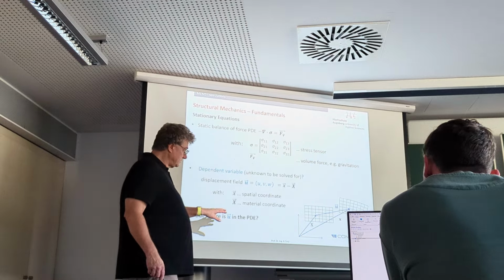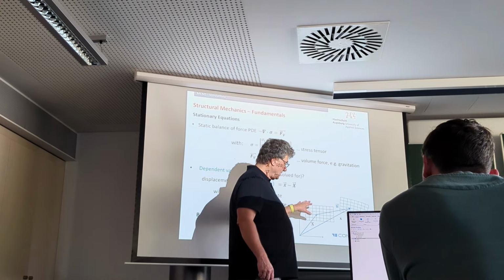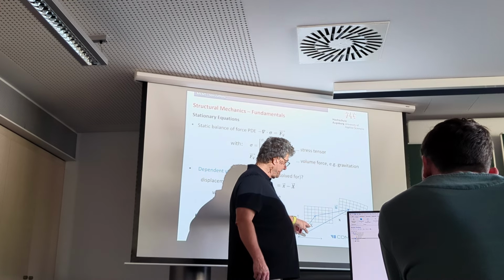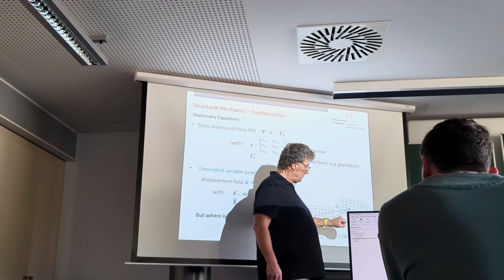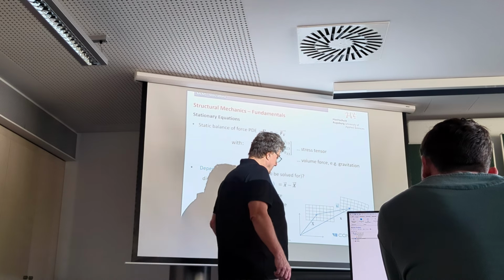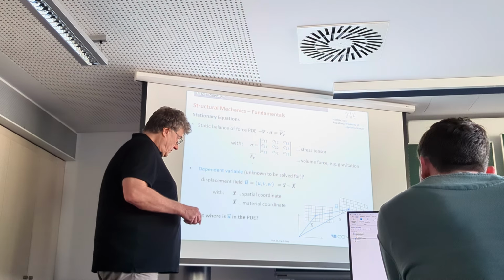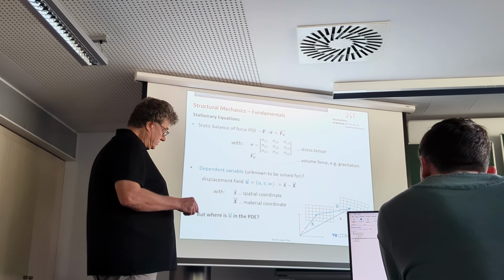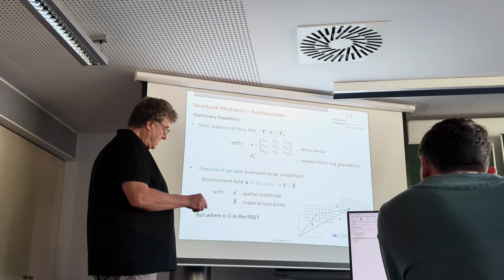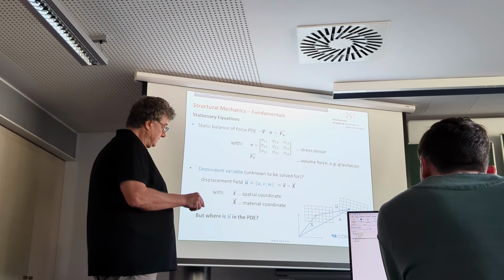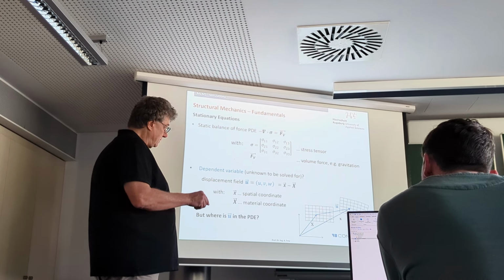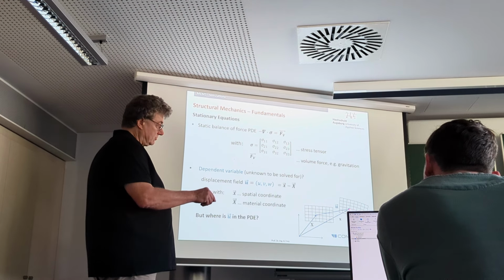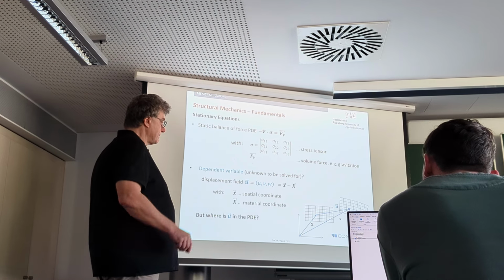So the coordinate system for the material frame, the undeformed, is labeled with large capital X. The deformed geometry is small x. So you see that particular point here, which is labeled with large X, after applying the force, it gets displaced by the displacement field or vector U, so it ends up being here, just moved from here to here.